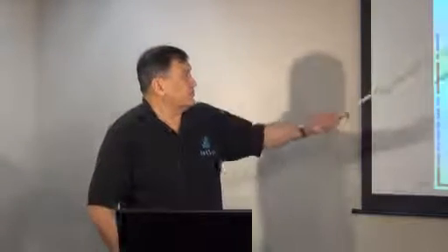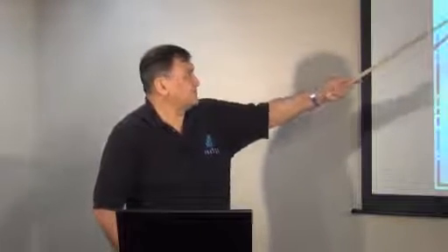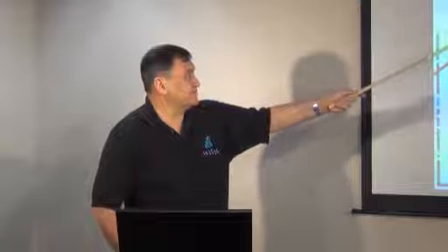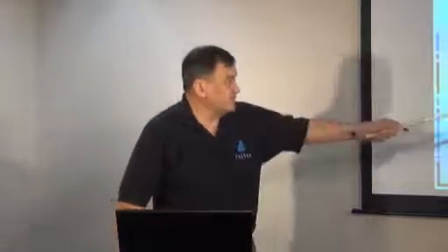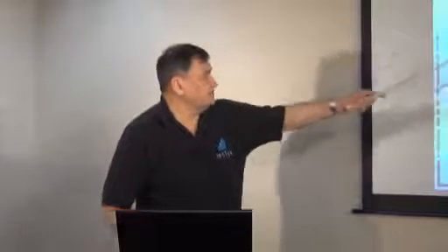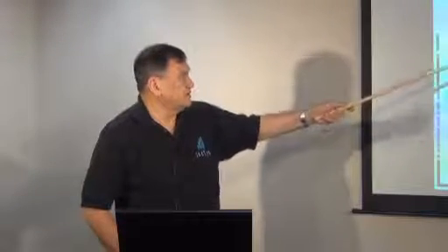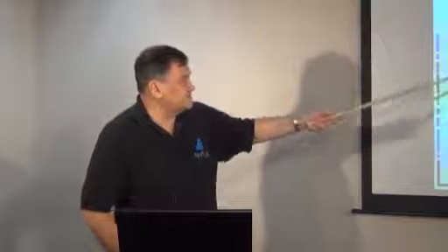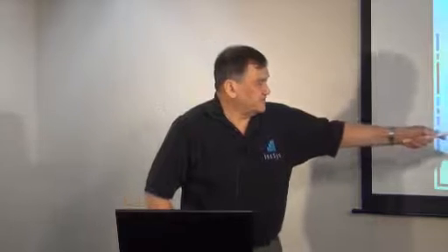On the other side, we're monitoring the real-time conditions. We have the flows, the megawatts, the megavars, the amps, the frequency, and the volts right throughout the system. And so the job of the reliability coordinator and the transmission operator, all as a team, is to make sure that you're very well aware of your limits and you're monitoring your real-time conditions to make sure that you're staying within the most limiting operating criteria. It's understanding that the flow on an interface can actually be governed by a number of different criteria. You as an operator have to understand which is the most limiting one.